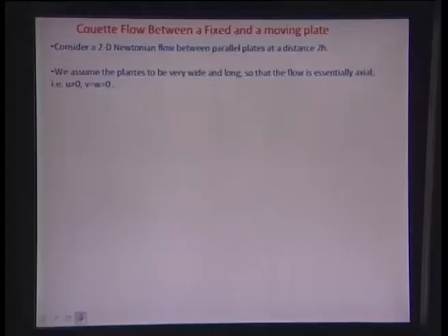So essentially we start investigating these microcapillaries with Navier-Stokes equations for different situations of pressure driven flows. Before doing that, just to illustrate a few conceptual things, we would investigate the Couette flow, which is essentially between two dimensional plates or surfaces, parallel plates at a distance of 2h, which has a fluid in between.